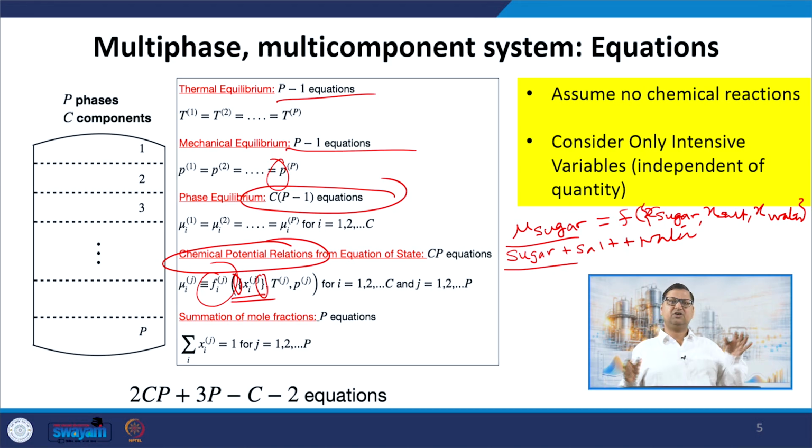So, I will do that, and there is some function that comes from the equation of state. I gave you examples of equation of state like ideal gas law and van der Waals equation of state, but for liquids there are more complicated equations of state. You may have heard of Redlich-Kwong equation of state, Peng-Robinson equation of state. There are further ones, more detailed ones like NRTL, UNIFAC, UNIQUAC. Whatever we are doing for that has to come from some experimental data or experimental analysis. That particular thing I am using here. So, this function, although it looks quite harmless, in fact is quite complicated, because the functional form can be quite complicated, but nonetheless it has to come from the equation of state.